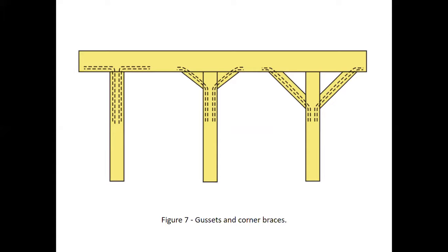And this kind of shows how gussets and corner braces affect stress and load distribution. So if we're building some sort of second level structure and we're putting posts underneath it, straight vertical post like this, if it's seeing a lot of movement, the stress lines will take a hard 90 and move left or right from the post. This could potentially have effects on the welds here and here. Generally, structures don't move that much, but if it's subject to a lot of wind, say here in Alberta, this may be something we would want to avoid.